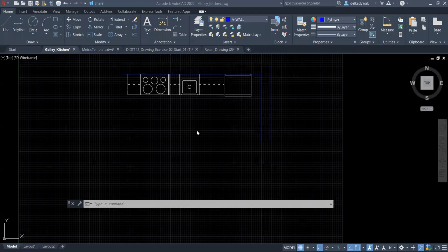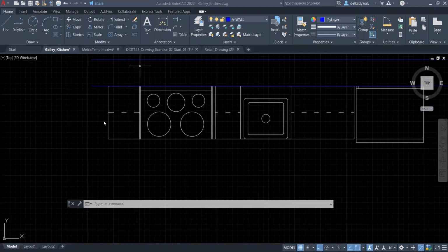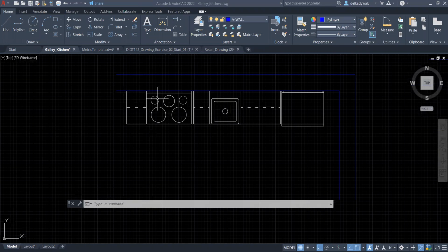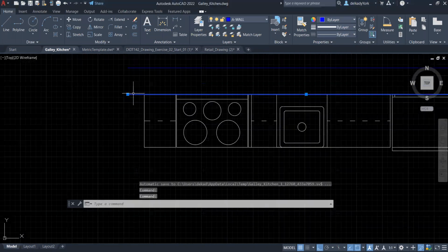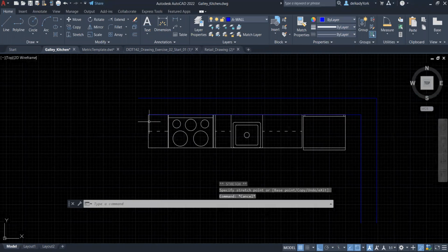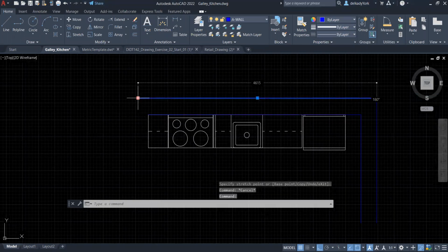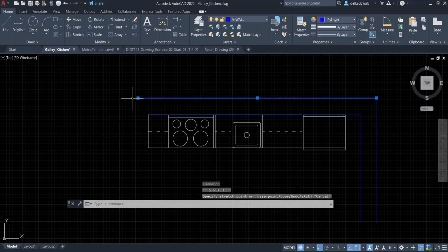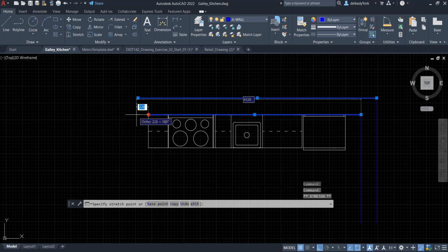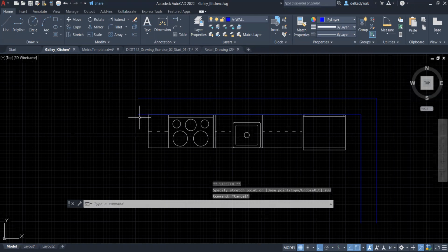Okay, so the second thing I'm going to be doing is that I will place an interior partition here. I actually extended those lines because those lines were like here, just like that. I wanted to extend them a little bit. So what I did is that I stretched this about 200 millimeters, but here I stretched this also to 200 millimeters, because where my line for the interior wall is going to start from here. So the interior line, I'm just going to click here, then I'm going to go down.